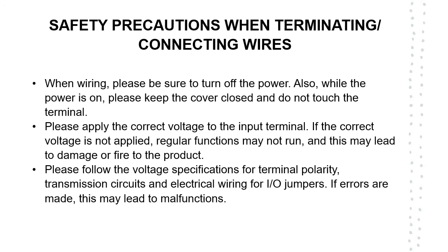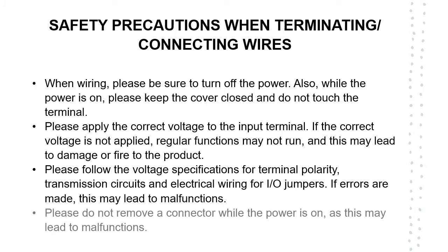Please follow the voltage specifications for terminal polarity, transmission circuits, and electrical wiring for input-output jumpers. If errors are made, this may lead to malfunctions. And please do not remove a connector while the power is on, as this may lead to malfunctions.